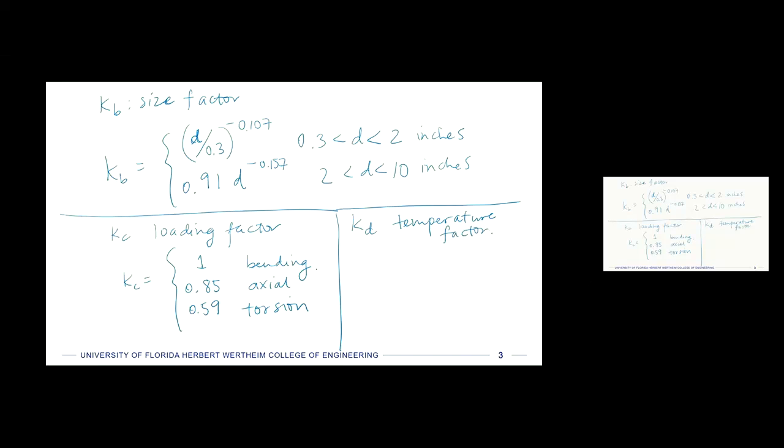And this can be thought of as not just a temperature factor, we don't know where it comes from, but what happens is as the temperature goes up, the material has that recovery at the nanoscale, and its ultimate strength and its yield strength drop off.